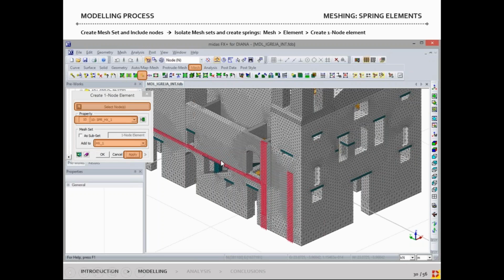So they would change the mode shapes, for example, or in the case of the later pushover analysis, the capacity curves. So this is a practical thing to do when you have influence of adjacent buildings, but you don't have enough computational capacity or time just to model everything, so you can try to represent them as an adjacent stiffness with this.